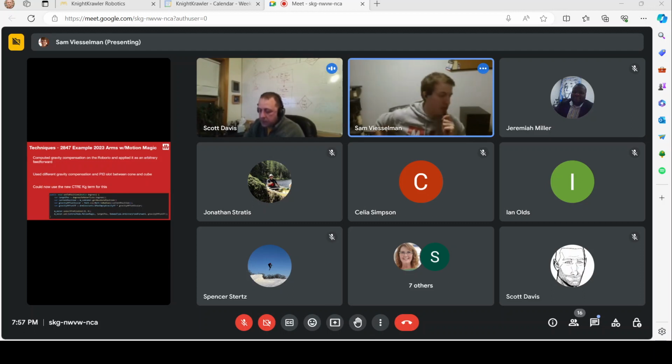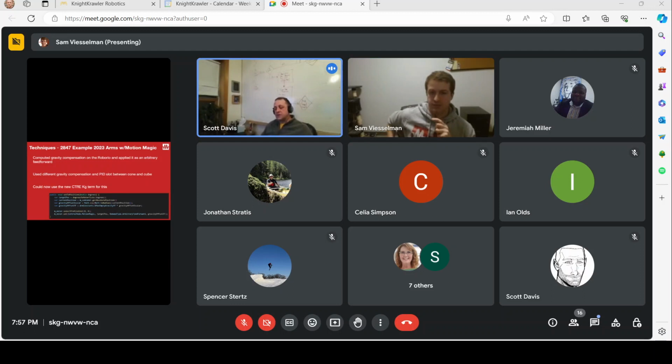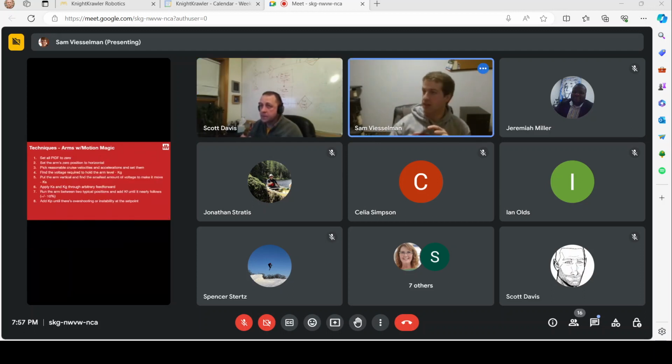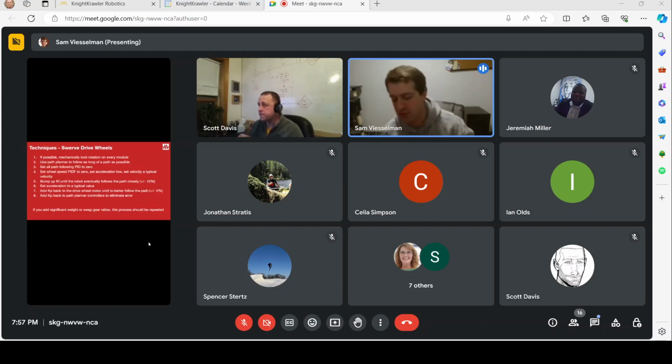Okay. And then do we have an example like this that we can use for the F, for figuring out what your feed forward should be? Yeah, honestly, you see this a lot in sample drivetrain code, but they'll calculate what your free speed should be, and they'll just say the feed forward is, let's say your max voltage is 12, just 12 divided by the max motor speed.